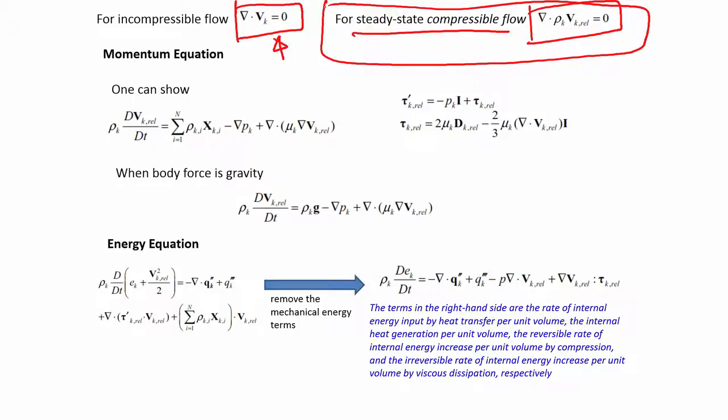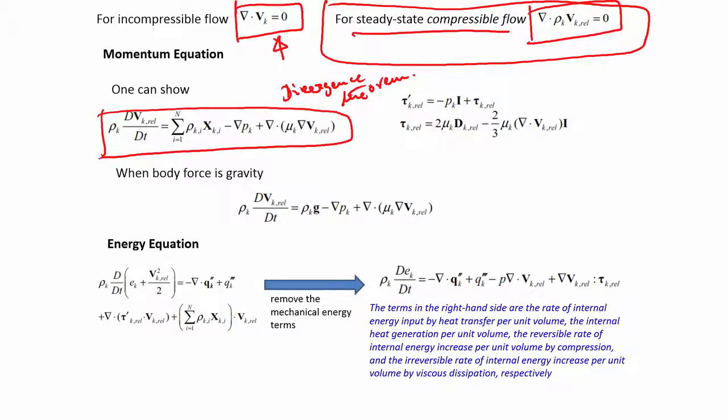I am not going to go into the details of the momentum equation. What we can do is apply the divergence theorem similarly, and we can show that this is the final form of the momentum equation. Here we have just done two things. This is still the material derivative of the velocity, like we explained in the last lecture. So, this is basically nothing but the convective acceleration.